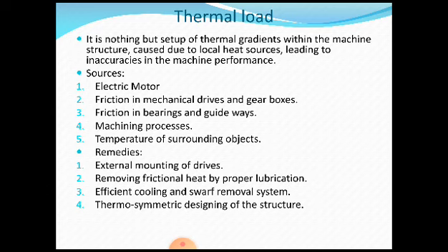We know very well that whenever we are going to use a motor or a gearbox or any other moving mechanisms, there is a continuous relative motion which can cause friction and which can in turn cause heat. So that has to be taken out of the CNC machine structure. You should see that the machine structure is not overheated, which can lead to the deformation of the whole CNC machine structure.